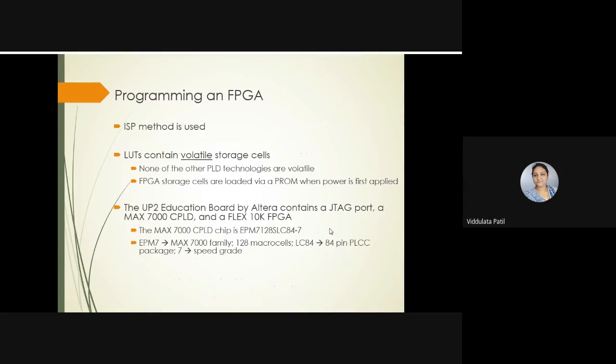Now, in an FPGA we are using the in-system programming method. That means you can program that FPGA on the board itself. There is no need to remove the FPGA from the board to program it.